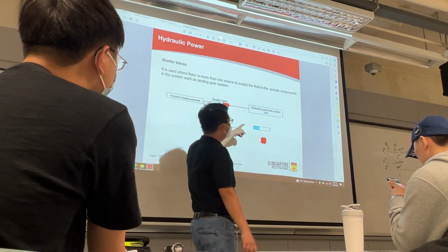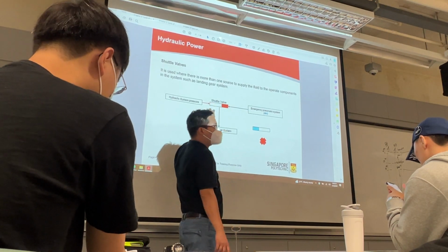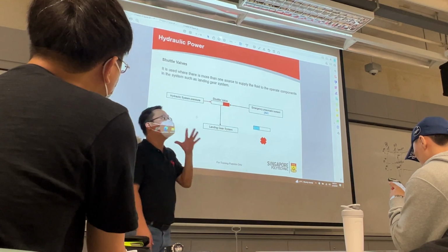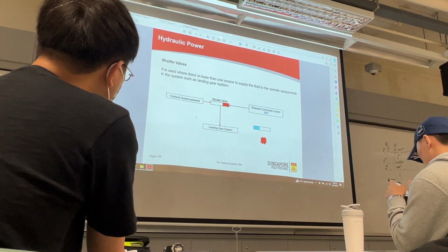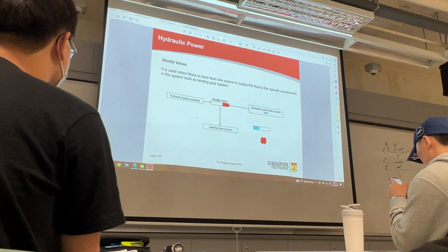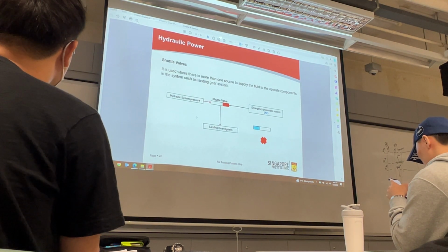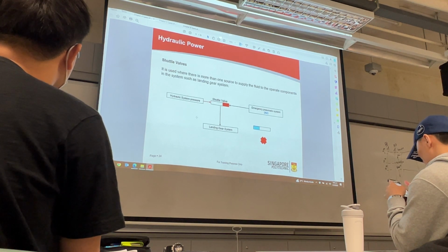After that, when you activate this pneumatic air, you will push this shuttle valve to the left. Then the pressure goes to the landing gear. Where did it go? It goes to the door actuators. These door actuators can be extended by pressure, hydraulics or air. So if my hydraulic is down, I only have air. The air goes in and extends the door actuator.